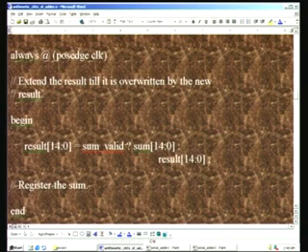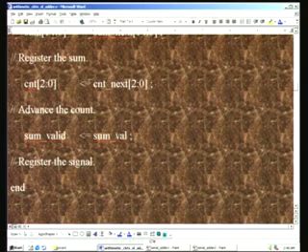So here we have one more for the result. This is not really required in an actual design, and it has been put only to make things clear. In this case, this is a parallel circuit to the other always block which we have seen, and we merely assign the result here depending upon the sum valid. Sum valid will be 1 only with the arrival of the positive edge of the clock, which we saw here in this particular condition.